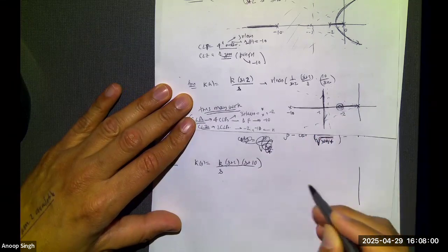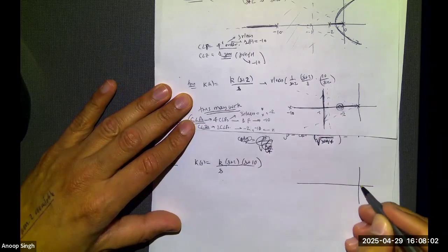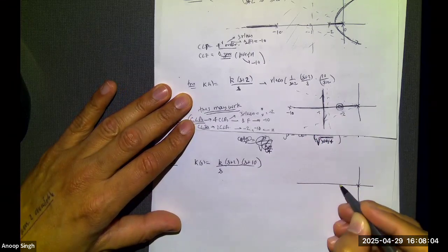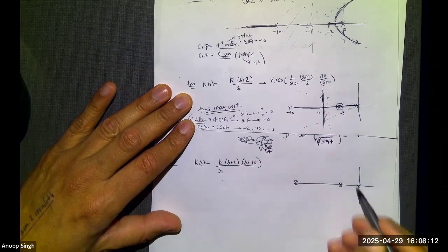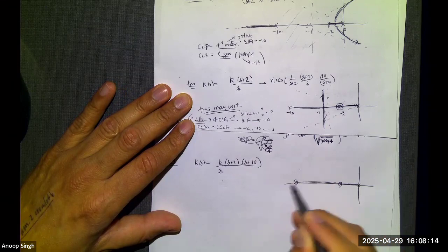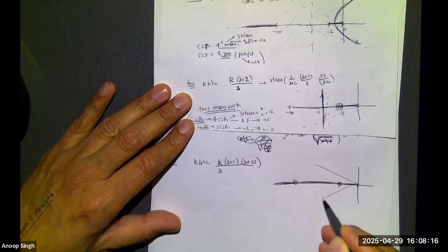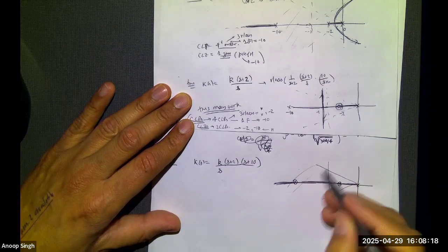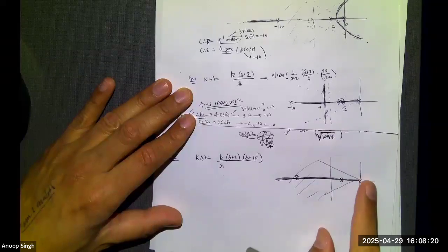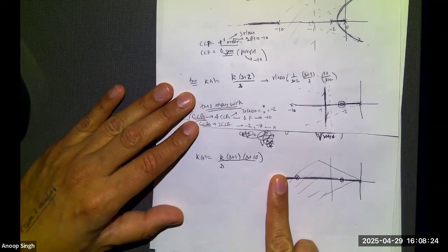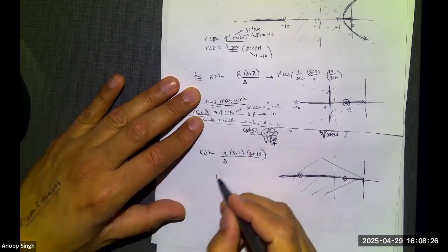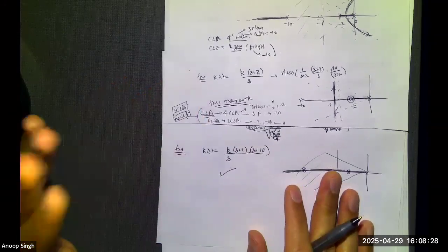Now the root locus will have a pole here from the plant, but the controller has a 0 there, and a pole here from H, but the controller has a 0 there. So my root locus is just a straight line. Well, that's for sure going to get the job done. If you increase the gain, it's going to stay over there. So this for sure would work, but let's try it out.